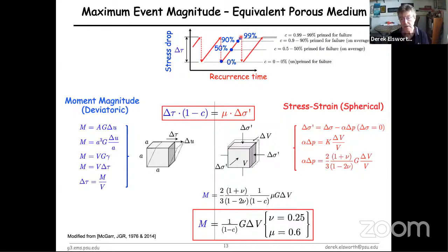And so we can study that by just looking at Mohr-Coulomb's law, where the shear stress change that you get in the strength is given by this shear stress change. Ignore this term for now. This term just allows for the fact that you might be somewhere on this trajectory. You don't have to make it all up at one stage. And we can look at what changes the effective stress. Well, pore pressures do, which we can relate to injected volumes.